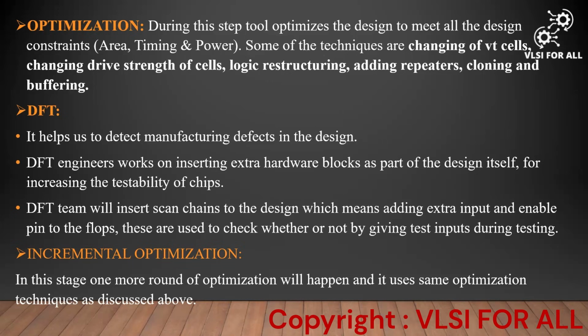So let's say we have some scan chain ports, six ports: three are input ports and another three are output ports. It will be decided based on the complexity of the design. The scan chain lengths will be equally divided, and whenever the input is provided to the scan chain input port, the output should come within this much time. Likewise, some expectations will be there according to how much time it takes to pass those inputs to the output ports of these flops. With this, we come to know that all the flops in our design are working fine.